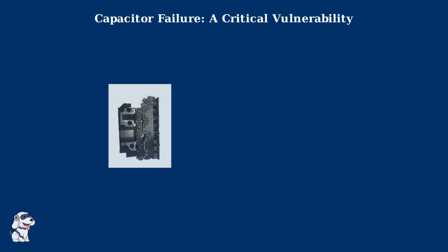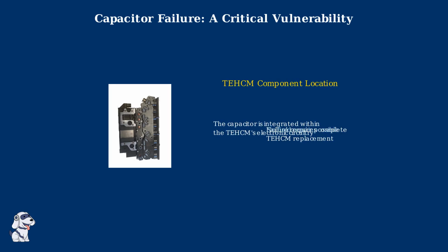The capacitor is integrated deep within the TEHCM's electronic circuitry, making field repair impossible. When capacitor failure occurs in units with build dates 7209 or 7262, complete TEHCM replacement is the only solution. This critical vulnerability highlights the importance of checking build dates before installation.